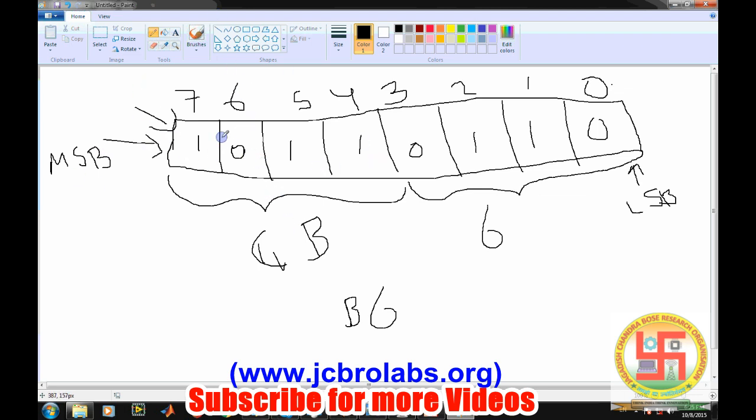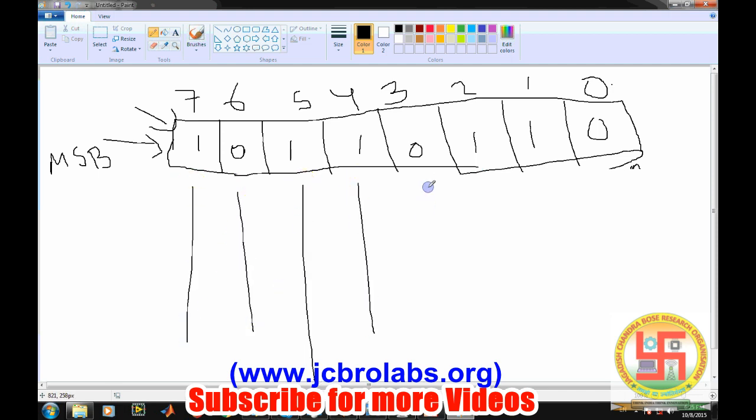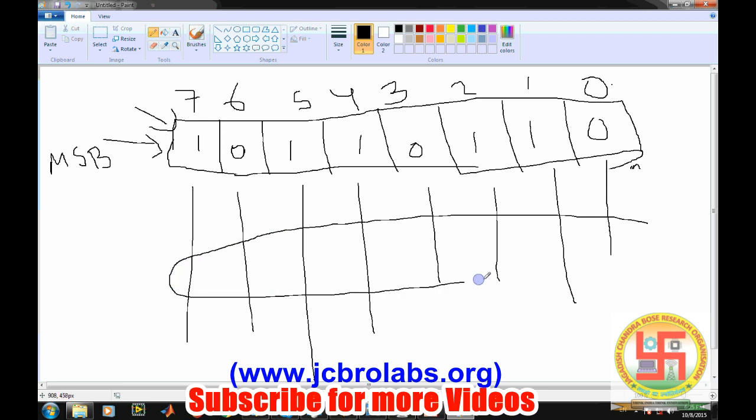That was about the data bus. If we delete all these things, what remains are the wires which will be used to carry this information. If it is a bus, there will be wires which will be used to read or write the information. There will be 8 wires, and the values on these 8 wires will determine the data inside the location. The bundle of these 8 wires is known as the data bus. So there are 8, so this is an 8-bit data bus.